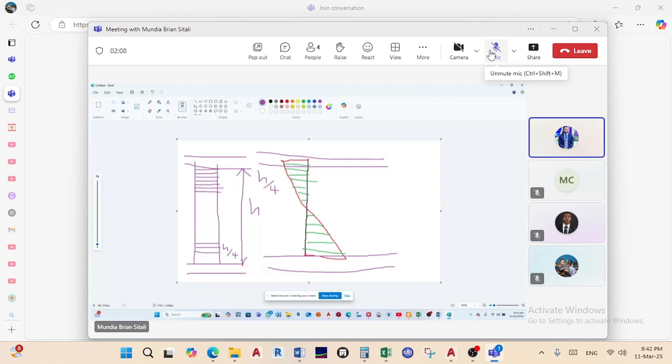So here you have closely spaced links. In an event that your link size is maybe 200, you usually want to space half of that here. So if you specify the links at 200 spacing, then you do 200 in this zone. This zone, h over 2, here you space them at 200, okay? Something like that. Then here you space them at 100 and here at 100.